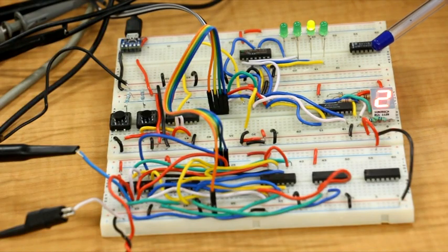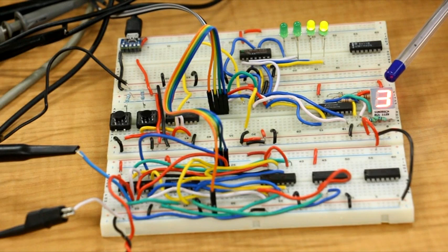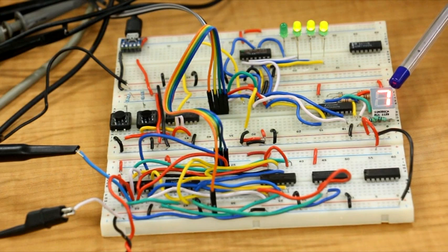So let's see how this particular synchronous counter is working. I have given a manual clock from the function generator, and the clock is half hertz, therefore you would have a much longer period to see. Right now you can see the 7-segment display, and the CBA outputs are connected to the 7-segment decoder 7447 and a 7-segment display. You can see the outputs here 7, 6, 5, 4, 3, 2, and then it goes back to 7.